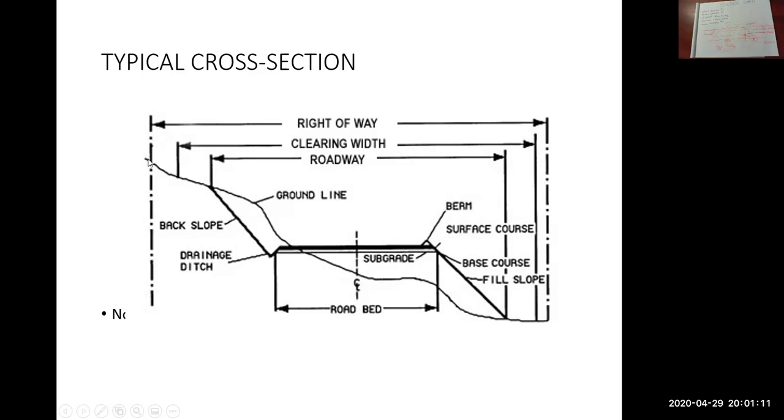Maybe this is on the side of a hill or the side of a mountain. So the engineer wants to build a road. Here's the center line of the road, so they've located it here. These various lines here are your asphalt on the top, then your base gravel and your sub-base gravel, right? For my notes that I did on my scratch pad.